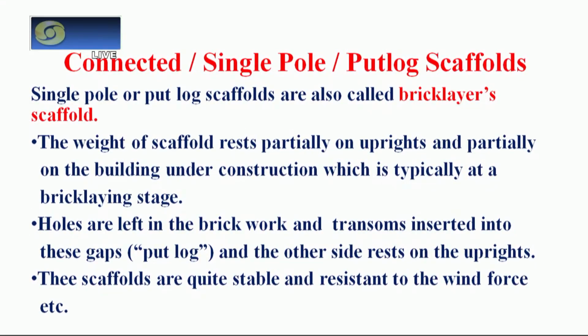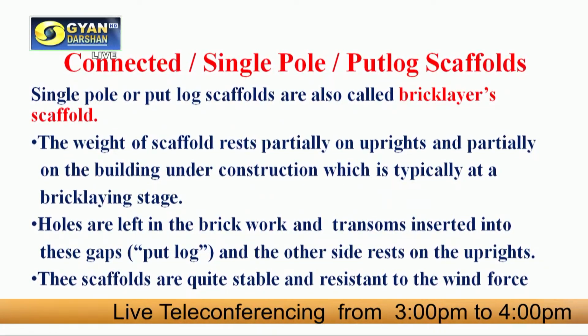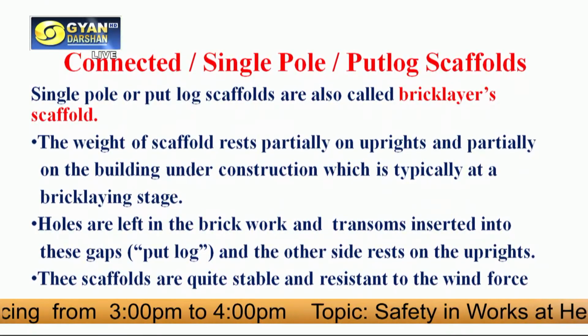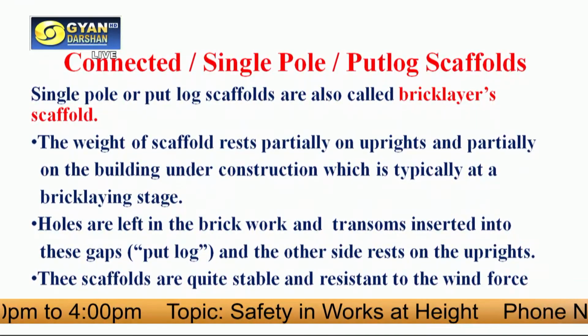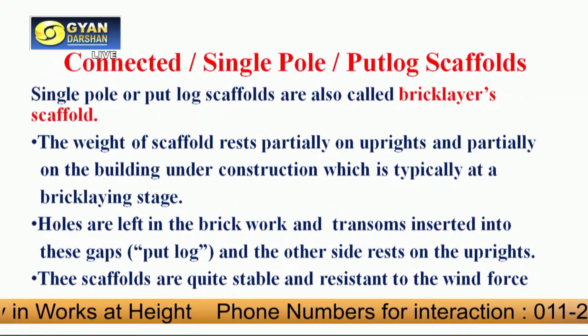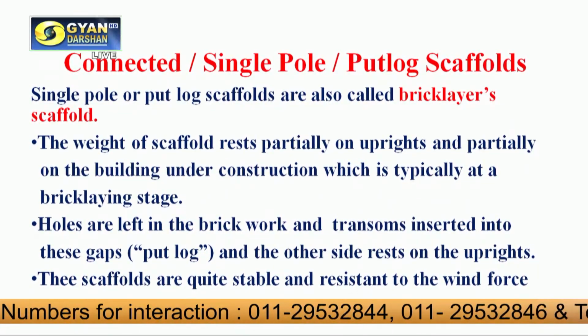Single pole because for its construction it is using a single line of uprights. And putlog scaffold because here we are using putlogs which are connected at one end to the ledgers, and the other end of these horizontal members is put into the wall to get support, to provide support to the scaffold and take part in the load transfer mechanism. So that is why these names are given to this type of scaffold.